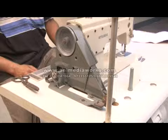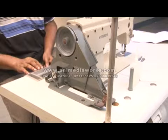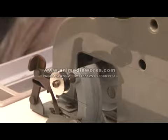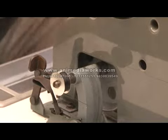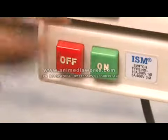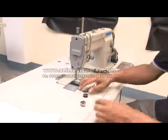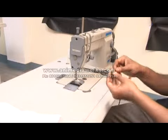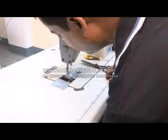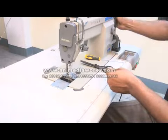Press the foot pedal to get the machine started to start winding the bobbin. Keep the machine going till the bobbin is fully wrapped. The thread should not overlap the bobbin edge. Put off the machine. Remove the bobbin. Open the throat plate. Insert the bobbin in the bobbin case and click it into position. Pull a few inches of the thread outside the bobbin case.